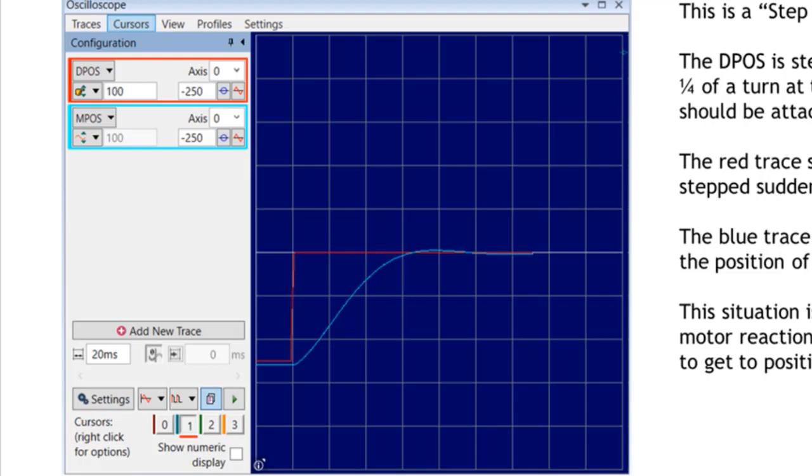And effectively, if it's got too much damping, in other words, the P gain's too low, then you would have what you can see there, where it goes up fairly lazily into position with not too much overshoot. There's a little bit of a hump here, so say it's getting to about there in position. So that's 5 lines on there, and it's 20 milliseconds each, so that's 100 milliseconds to get to position.